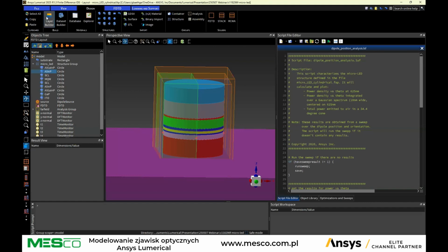Basically, you have the layout mask that defines all the different layers, and we can define what is called the process file. The process file will include all the information about the layer definitions, what materials for each layer, and what the thicknesses are. By combining a GDS file and a process file with a layer builder, you simply automate the creation of a stack like this. Here we didn't use that.